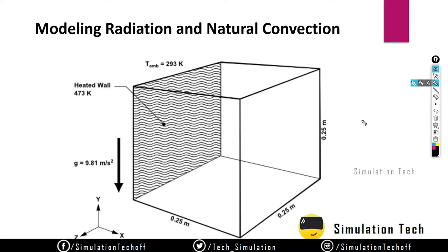So like always, we have the MSH file. You know that the MSH file includes the geometry as well as the mesh data. Also, it has the named selections, everything. So we can directly enter the CFD module and assign the viscosity and then the energy equation. These things we can do in that process. And also we are interested in viewing the velocities and then the temperature difference of the air. Okay, so inside we have an air structure.